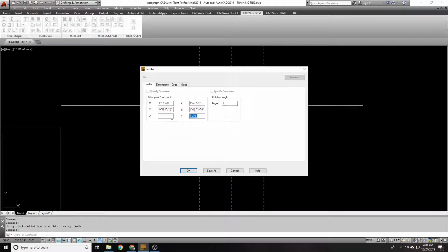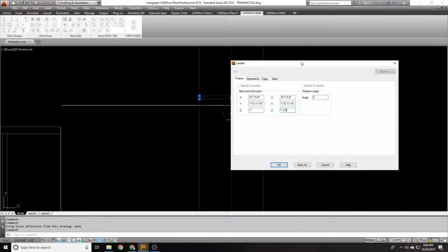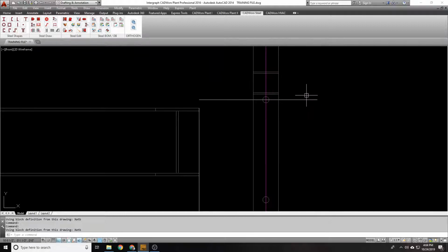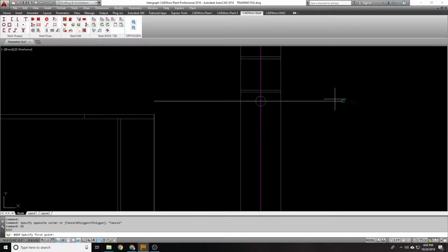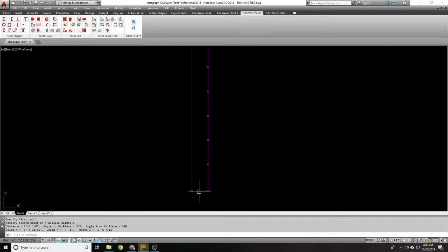Also, your company may use the center line. If they do, just raise it up 3/4 inch instead of 3/8 inch. So center line of the rung, top of grading. Okay, keep that in mind, that even though this says it's 7 feet, it's not exactly 7 feet. But you'll notice if I measure, this is actually going to be 7 foot 1. It's kind of weird how that works.